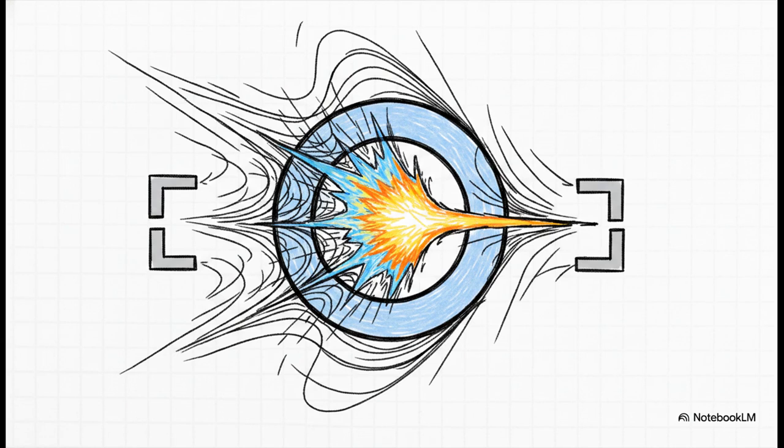Well, the answer is the coil's stored magnetic energy violently collapsing. See, turning the relay off collapses the current suddenly. The spark you are looking at is quite literally the physical manifestation of self-inductance fighting back against that collapse. The magnetic field is rapidly dumping its stored energy right back into the circuit, and that spikes the voltage high enough to just jump the physical gap you just created.